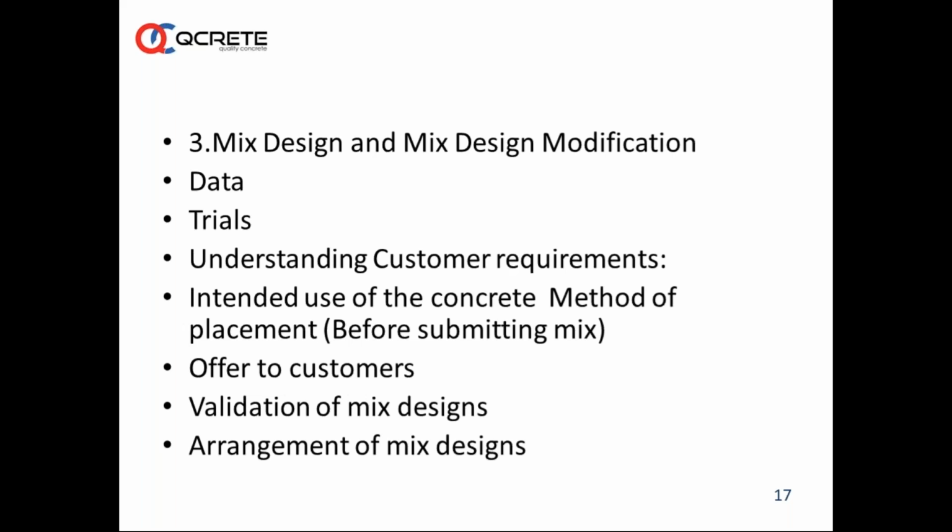And we have to understand what the customer wants. Intended use is very important. If we don't do this, we will be heading into disaster. For example, we had a problem long back where the customer asked for M25, we gave M25, and after 1 year he called to say that dusting was taking place, with a lot of material coming off the concrete floor. When we went and visited, they were using a lot of wheelbarrows and heavy vehicles on the floor, and this was not told to us before we supplied the concrete.